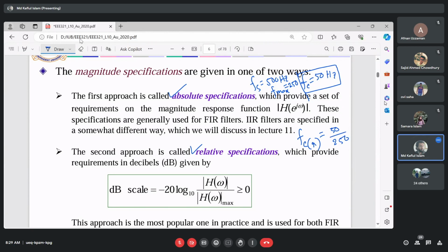So when you do normalization, or take the relative value with respect to any maximum value, your maximum relative value will be 1, because your maximum frequency is 250. It cannot be more than that, and you are actually normalizing the value with respect to your maximum frequency. So the value of your relative frequency will always be 0 to 1. Similarly for omega max, what will be the value of angular frequency as mentioned before? It is minus pi to plus pi, and we do not take the negative frequencies, right? Because they do not make sense. So it is actually from 0 to pi.